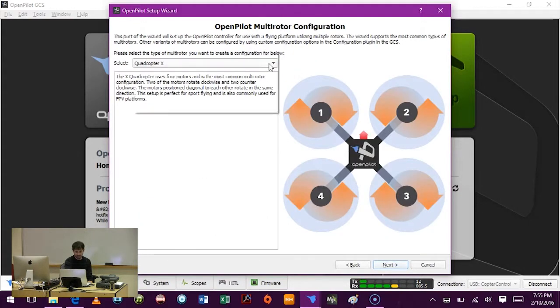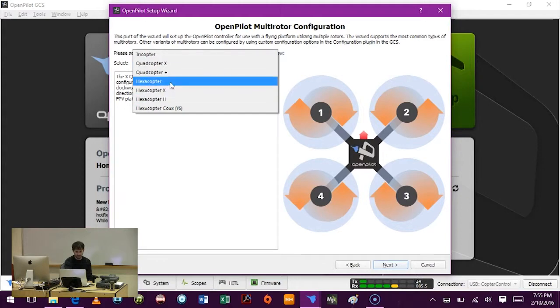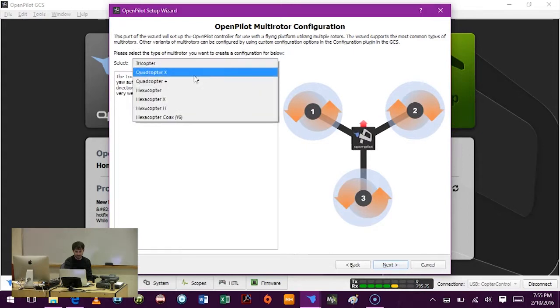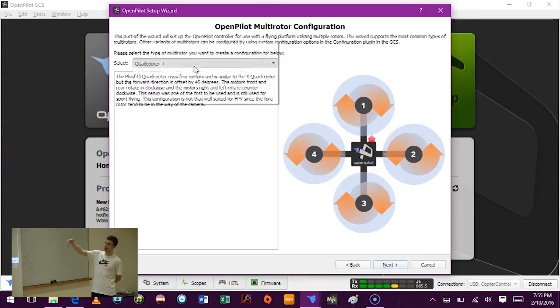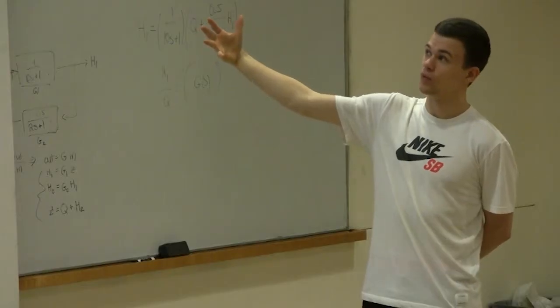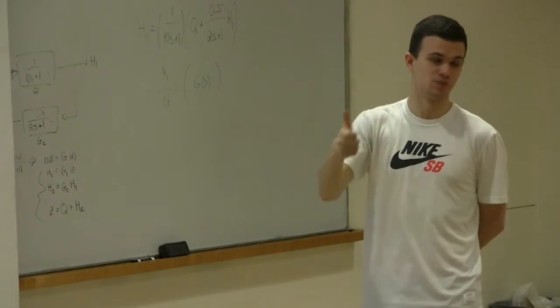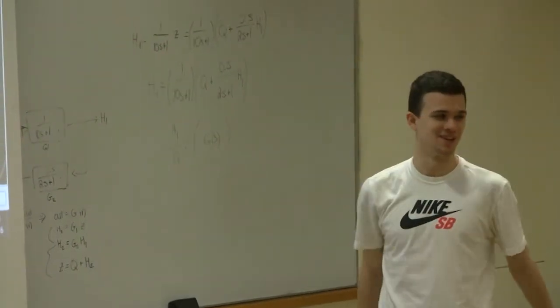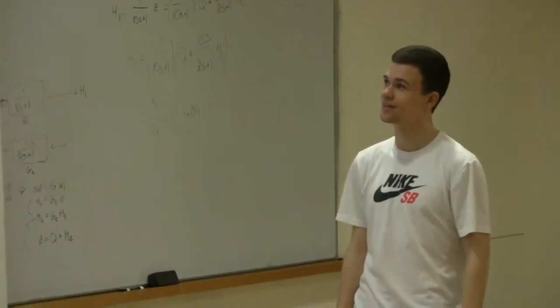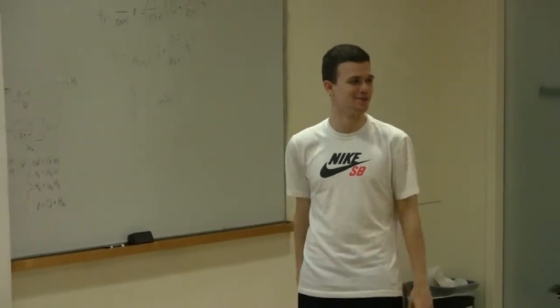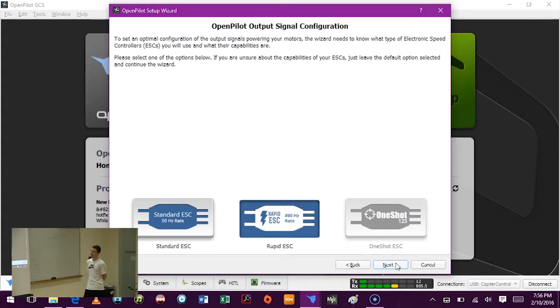Okay. And go through here, show you guys different options. A little more fun stuff. And make sure you get the motor number right when you're plugging into the flight controller. On the X8, for example, we had 2 motors switched. So whenever you turn the throttle up, it would just flip over because it's expecting different things. And that took 15, 30 minutes to figure out. It was really annoying because it's like, why is the quadcopter flipping over every single time? Flipping is always an indicator of the wrong motor.